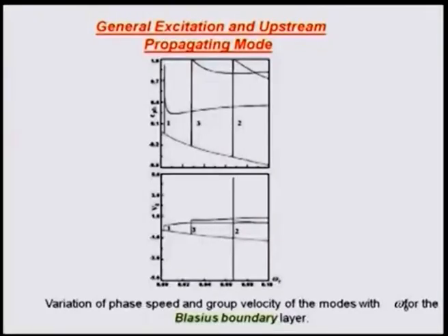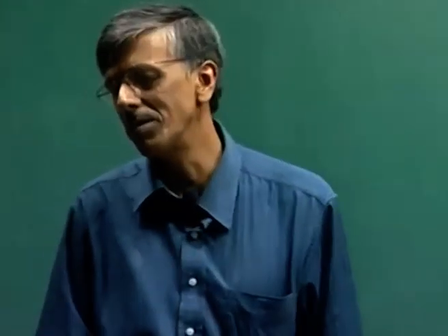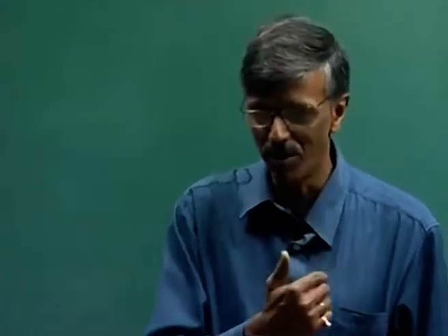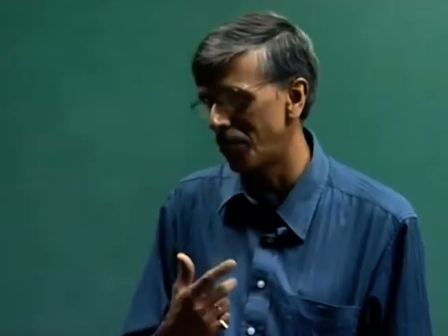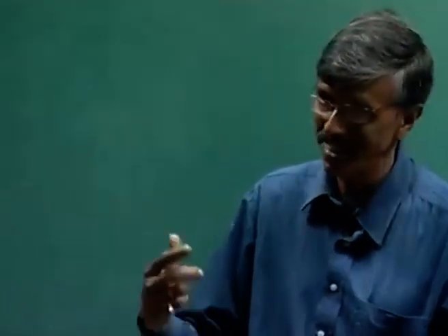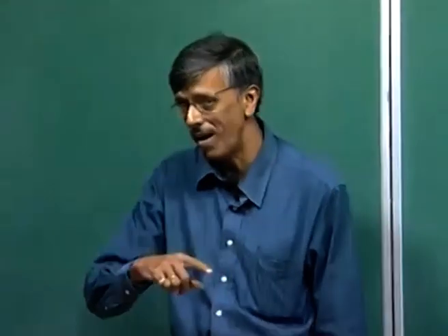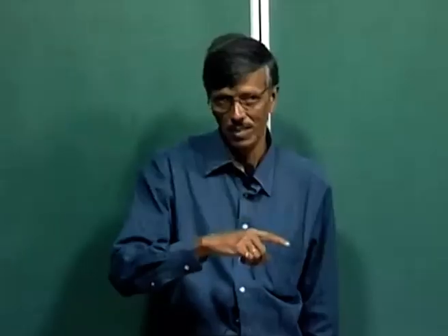What you actually should do is to calculate the group velocity. If you calculate the group velocity, you find that those modes in the left half plane have a value less than 0. So, that means what? These modes are propagating really upstream. So far, we have been talking about phase propagating upstream, but now we are seeing that the disturbance also propagates upstream. Now, corresponding to that, if alpha I is negative, then what do you have? You do not have an unstable mode.